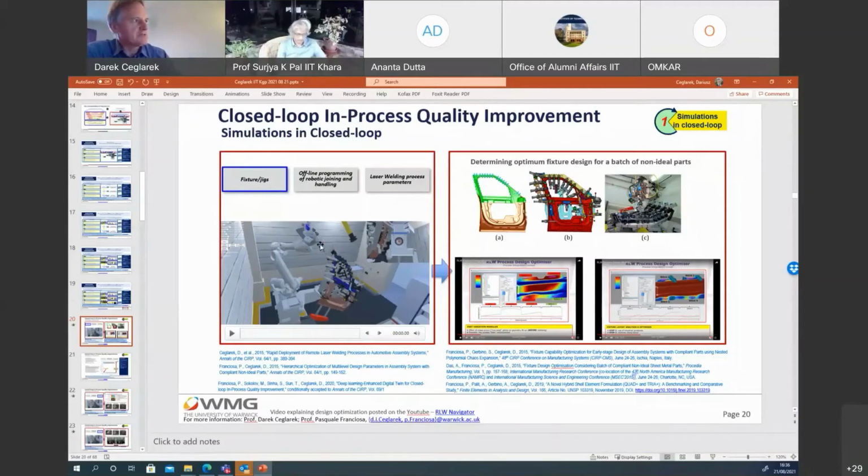Maybe just one word on this remote welding, because remote is, as you probably know, one-sided and non-contact. Therefore there are much fewer constraints for design people. I don't need two-sided contact, where I have to have access from both sides and touch the part. Here, we don't need to touch the part from both sides. However, the challenge is that if we don't squeeze these components under error conditions, the gap between components changes. If this gap changes, suddenly there are a lot of defects if you cannot consider this. So without a good digital simulator, this becomes a challenging task.